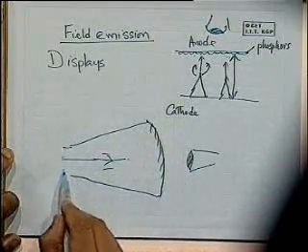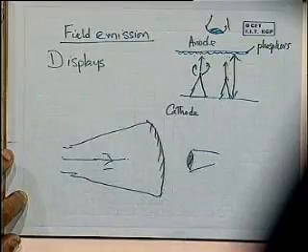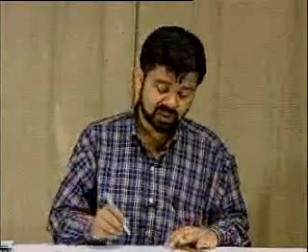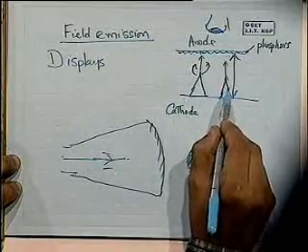What is the primary difference between this and this field emission display? What's the big advantage? The second one is bulky, right? The monitor takes up so much space of your whole computer device. That's probably the bulkiest part of a computer. So what they've come up with is now flat panel displays that are based on this field emission technology. There are other technologies for flat panels based on LCDs and things like that, liquid crystals, which we won't go into. But some companies are actually marketing displays that make use of field emission, because you can create a really compact flat picture tube.